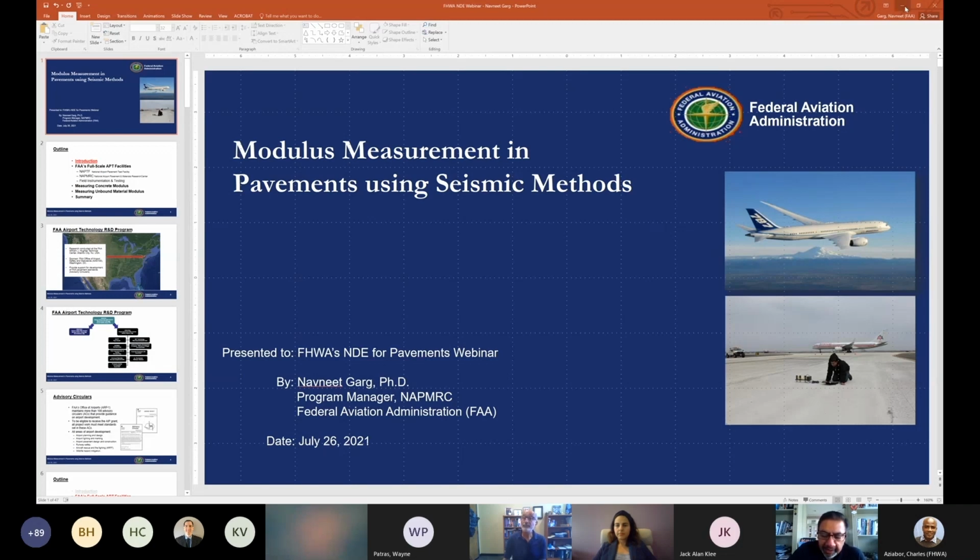For a 20-year design life, we were mainly looking at structural life. Now, functional life will also become very critical. So we are trying to come up with an index that combines both the structural and the functional part to estimate when you would consider your pavement failed over a 40-year design life. For that, we are collecting material samples from different airports and looking at their PCI data collected over the years and analyzing that so that we can come up with the requirements for a 40-year design life.